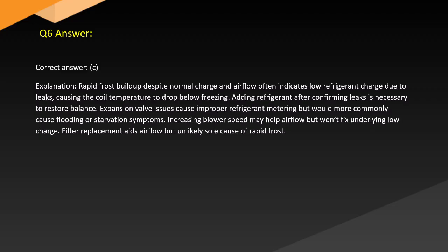Expansion valve issues cause improper refrigerant metering but would more commonly cause flooding or starvation symptoms. Increasing blower speed may help airflow but won't fix underlying low charge. Filter replacement aids airflow but is unlikely the sole cause of rapid frost.